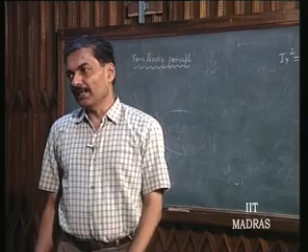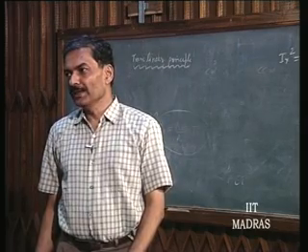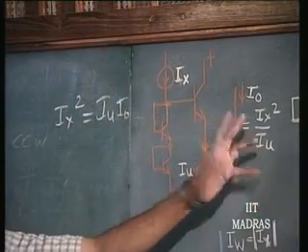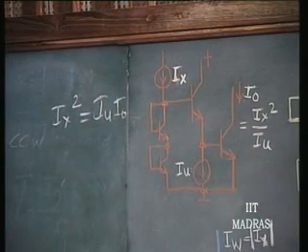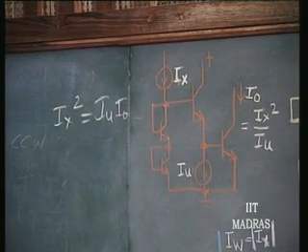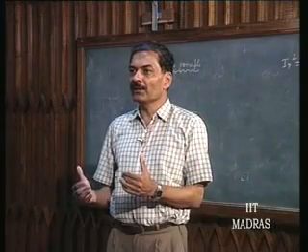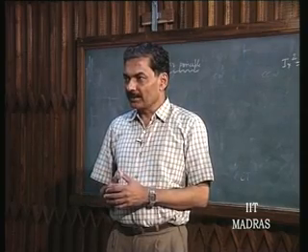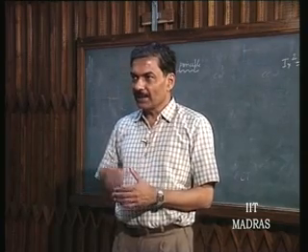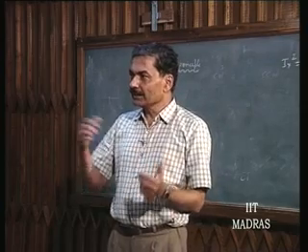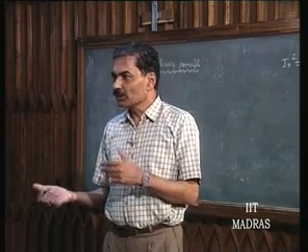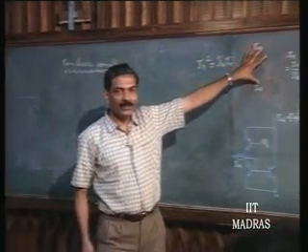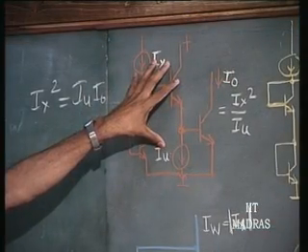So, this is a simple operation of squaring. If Ix is your signal current and IU is the reference current, you are just squaring the current. This kind of signal operation is required when you want to find out the RMS value of a given waveform or anything. So, you have to square and then integrate and find the square root. These simple operations can be straight away done with the help of this translinear principle.